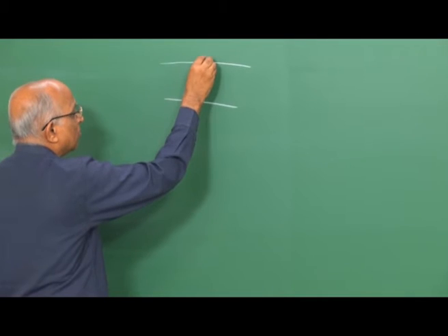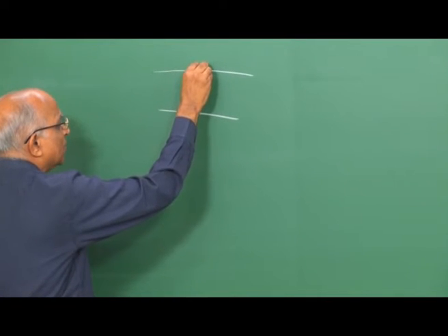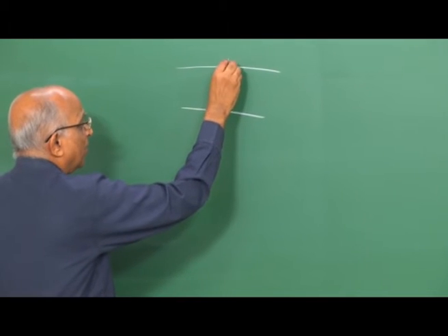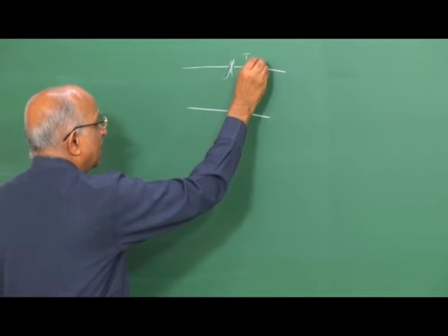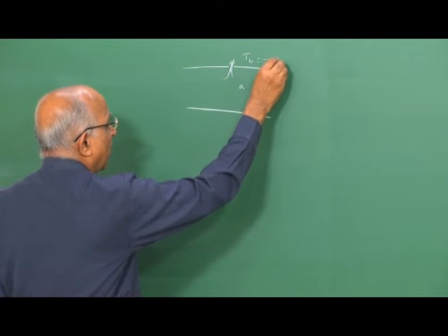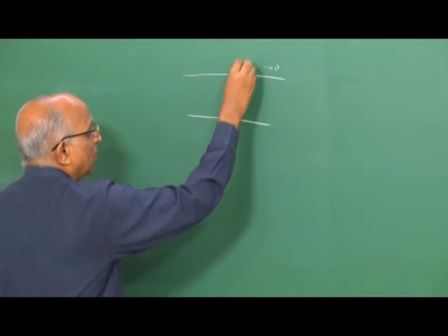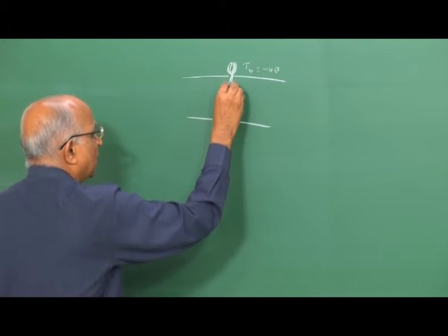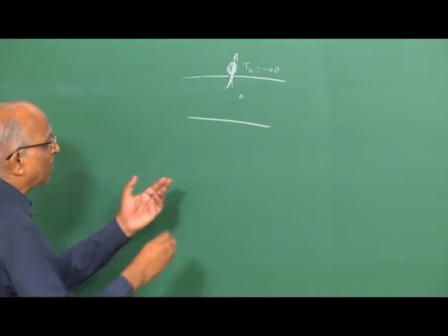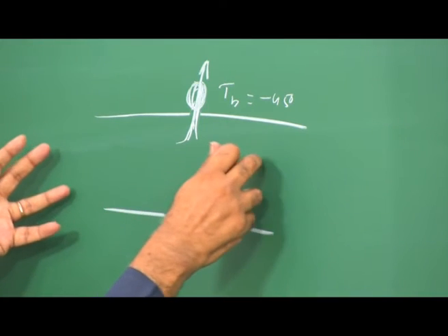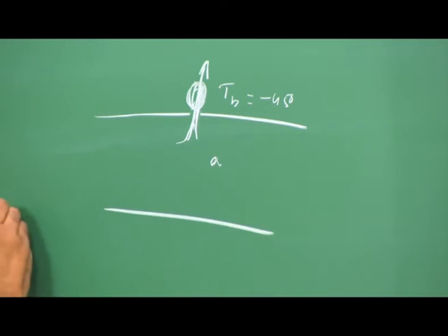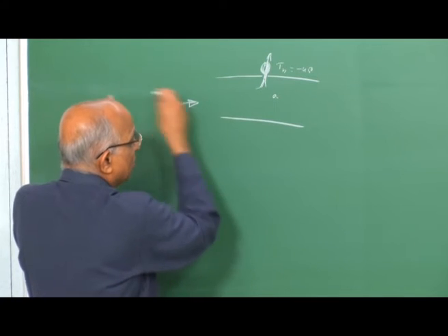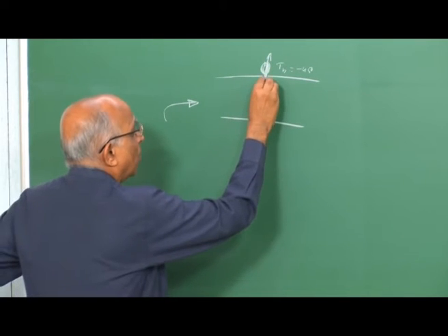When the liquid propane comes out, it is at the ambient temperature corresponding to the high pressure here, but its boiling point under the ambient condition is something like minus 45, and the ambient temperature is higher over here, therefore it flashes into vapor. Therefore, you have the leak taking place, and the leak does not take place at 0 time. It keeps on leaking, considering the amount of fluid in the pipeline, and the fluid is pumped by a station which is quite a distance away from where the leak is happening. You have a constant source of leak.